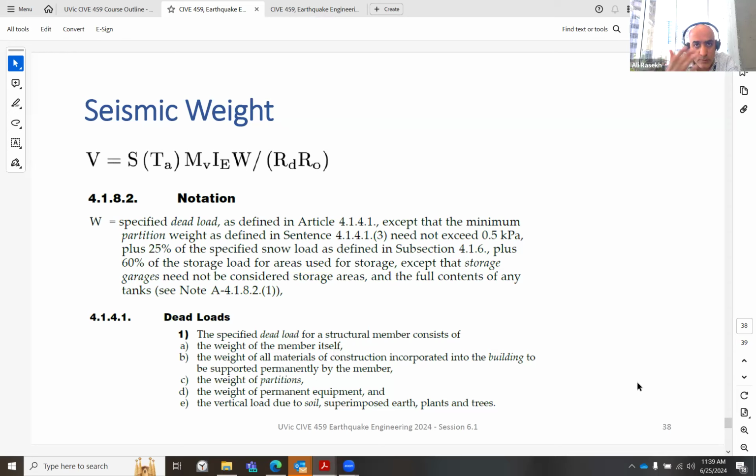We always assume, the society assumes that like a building should at least survive 50 years, and then we want 2% chance of it. Like even if an earthquake with 2% chance happens, we want to protect that building against that earthquake to be uniform.